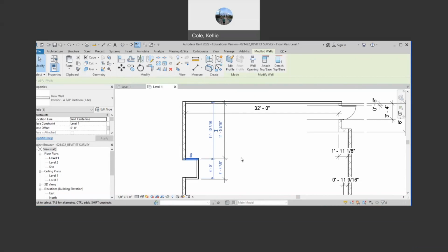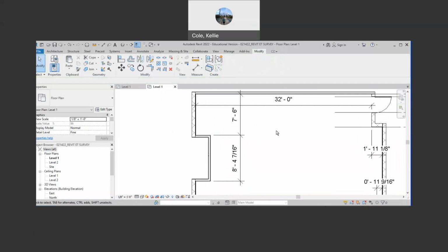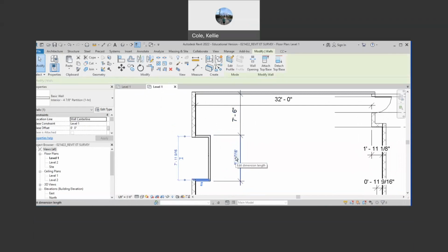So you're just simply going to select the wall, and then the dimension, you have two sets of dimensions, but it's the one with the black line. You're going to touch that numeric value and type 90 inches, enter. So for this command to work, you can only touch one wall. And then this is 15 inches wide. So I'm going to select the bottom of that pilaster wall, plan south. Hover over the numeric value of my dimension and type 15 inches.